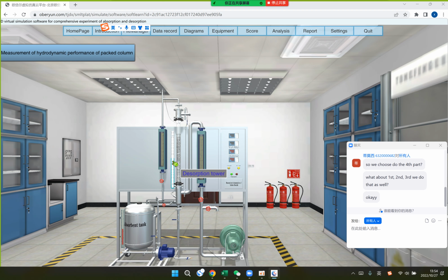The U-tube pressure meter contains two water columns or liquid columns. It can contain water or other kinds of liquid like mercury. So we can calculate the pressure differences by delta P equal to rho g h, where rho is the density, g is gravity, and h is the height differences of the U tube, which I think you already learned in the theory part of this course.